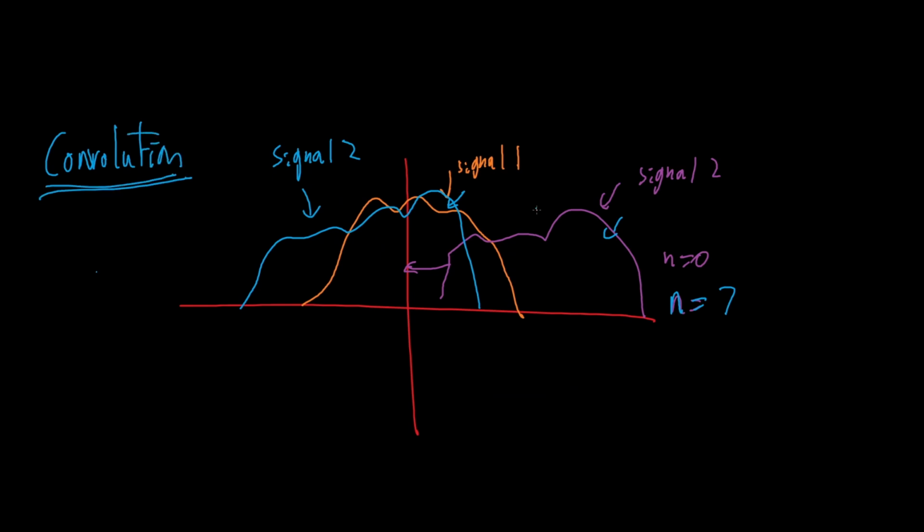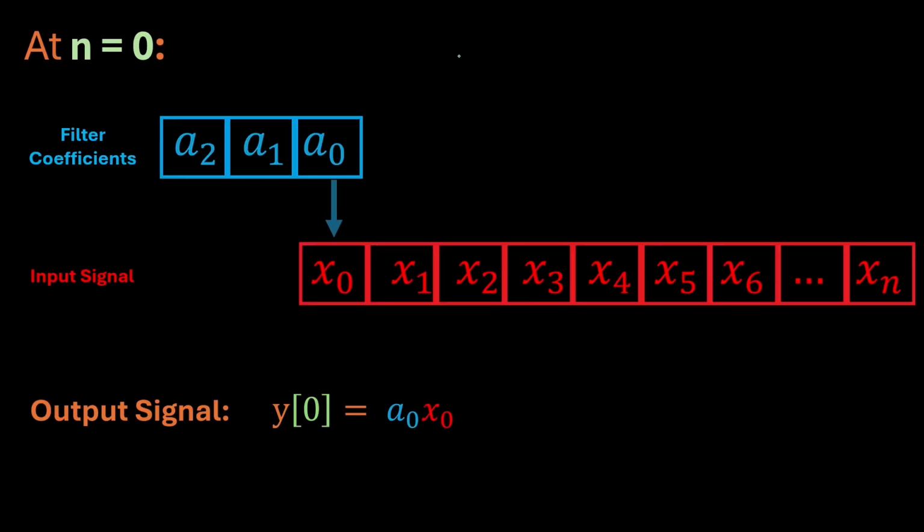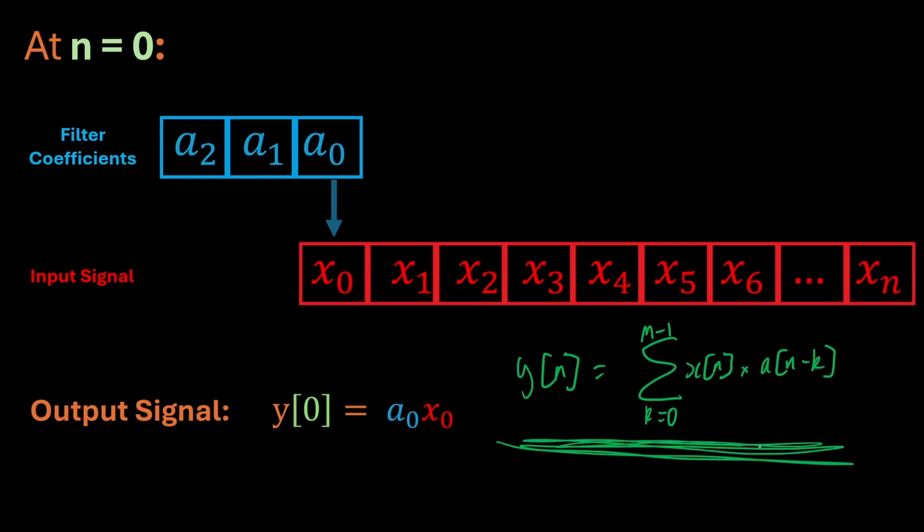So to get a clearer understanding of array convolution, so in a computer you would be dealing with arrays, not just these random graphs, this animation I'm going to show you hopefully will animate the convolution: the filtered signal equals the summation, k equals 0 to M minus 1, of a_k multiplied by x(n minus k). This animation should explain what this formula basically does. So let's watch the animation.